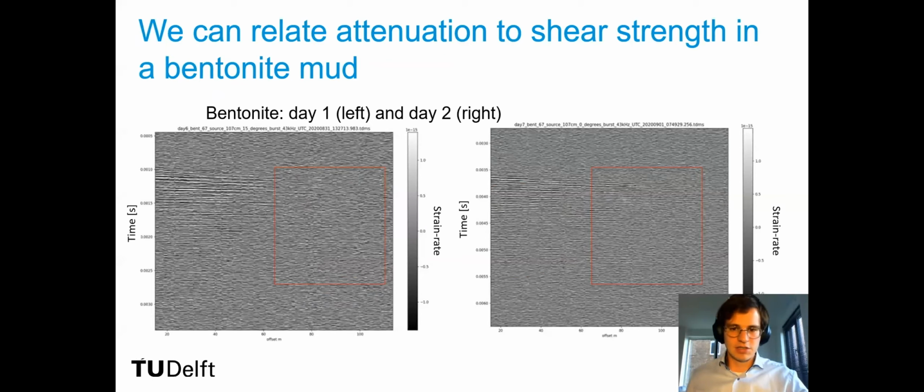In the middle here, the upper figure is the DAS strain rate profile. I marked out the P and S arrivals, and I just want to draw your attention to the area near the apex, where you can see this signal with reverse sign. I also chose two vertical lines, symmetric about the apex, and plotted the traces at the bottom here. I also marked the P and S, and you can see there's some signal here, but not very strong.